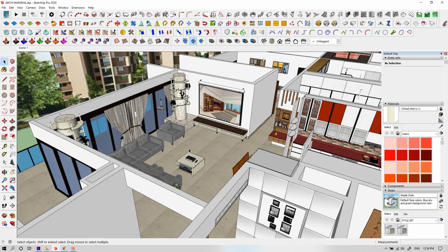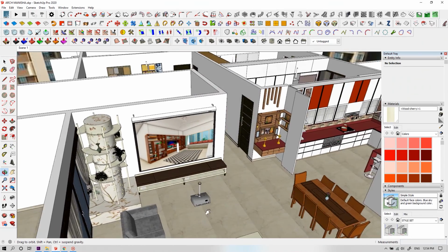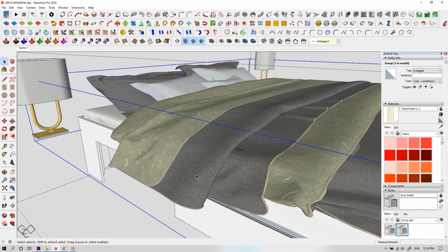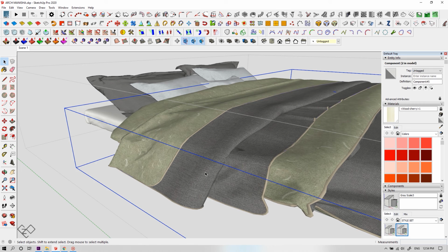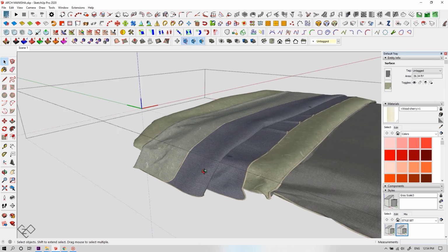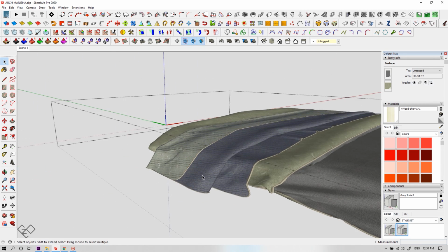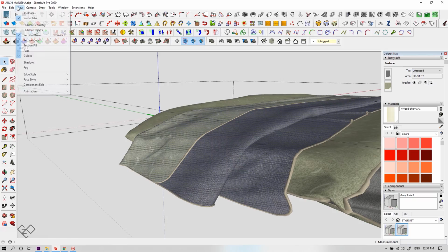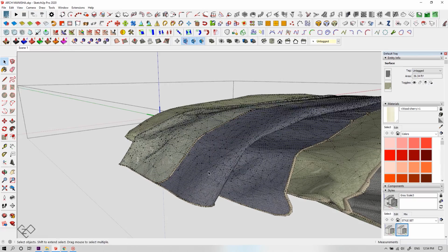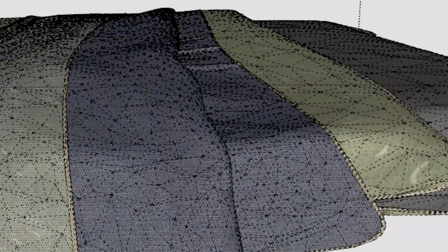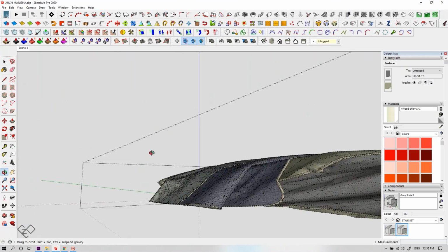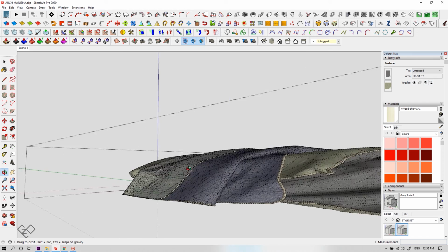Now let's see how to avoid picking components which will make your file unable to work. The reason behind that is, if your component consists of too many polygons in a mesh, SketchUp struggles to load your file each time you move around your model. On the outside, these components seem harmless, but when you turn on the hidden geometry, you can see the polygon count is too high for our PC to handle. To avoid selecting such components, you need to be cautious before selecting your components.